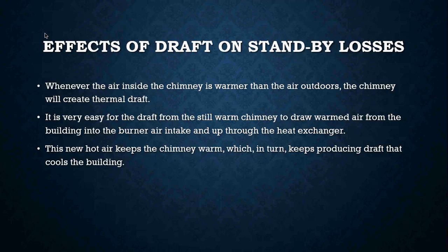Okay, effects of draft on standby losses. That's simply when the furnace is just sitting there waiting for the next call for heat. Whenever the air inside the chimney is warmer than the outside, the chimney will create thermal draft. This is very important: the draft from the still warm chimney draws warmed air from the building into the burner air intake and up through the heat exchanger. This new hot air keeps the chimney warm, which in turn keeps producing a draft that cools the building.